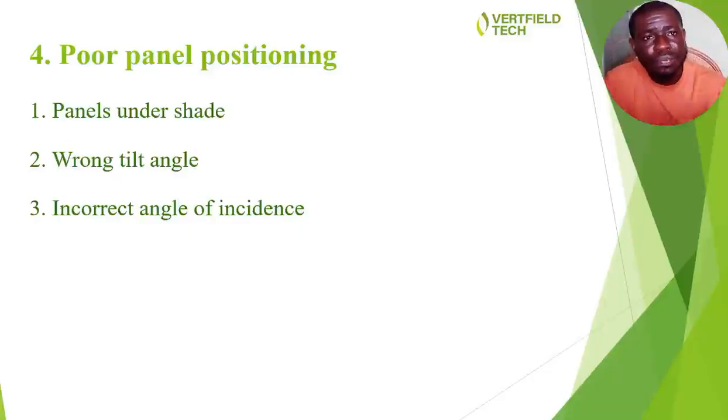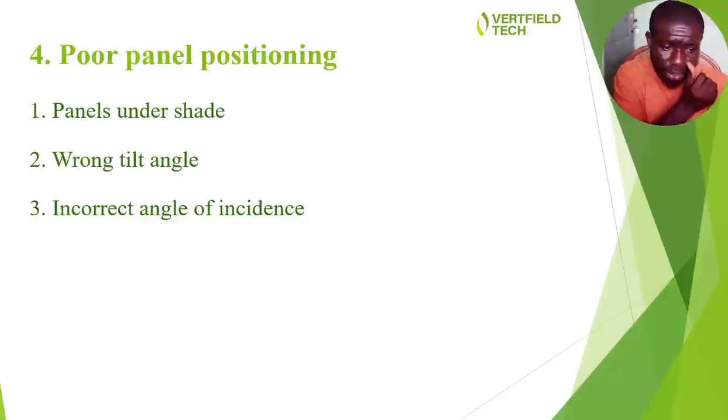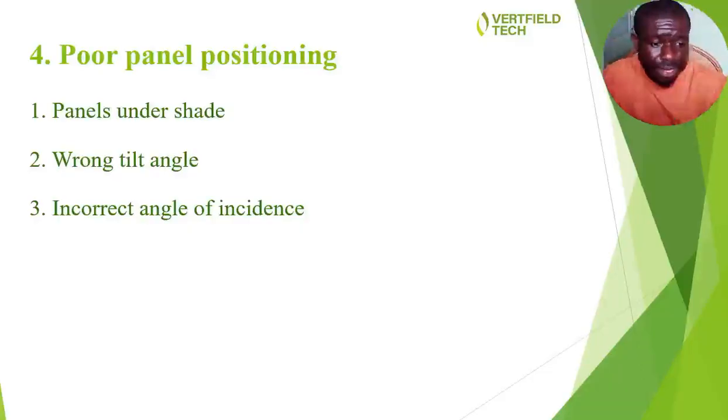In the field of solar system installations, when you are invited for a site survey, one thing you should always look out for is where you will be installing your solar panels. On no account should you install your solar panels where it is going to be shaded. Panels under a shade might lead to system failures.